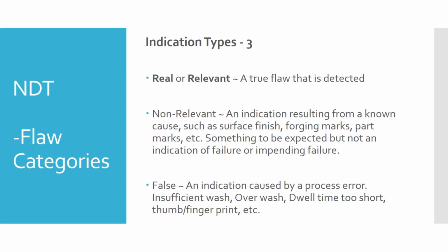Okay, so relevant, a true flaw; non-relevant, geometry of the part or surface finish; false is caused by a mistake. And for every indication that you discuss in your lab reports, you're going to have to classify it as one of these three.